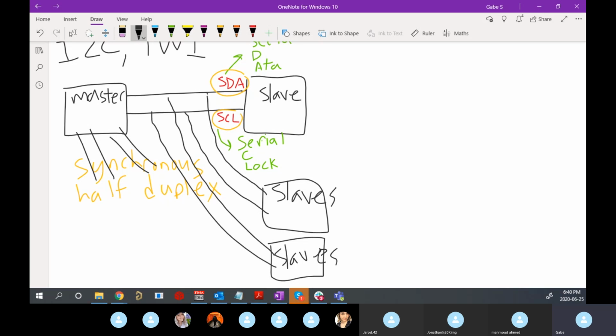And that's usually what you would have to do with something like UART, although there are theoretically ways around that. But the beauty of this protocol is that it's just 2 wires and you can attach so many different slaves to it. So it's super cheap in terms of pin count and amount of wires you need. So if my master were some microcontroller, it would only need 2 pins, and it could theoretically talk to about 128 different chips just with those 2 pins. And that's why people love it. It's a great protocol, just a little bit complicated.